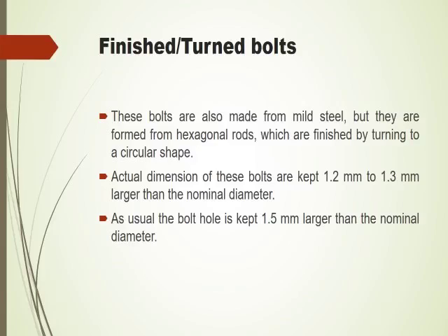And while coming to the bolt hole, it will be kept 1.5 mm larger than the nominal diameter, as we discussed before. The bolt hole is to be of a little bigger diameter than the bolt so as to insert that bolt into that hole easily.